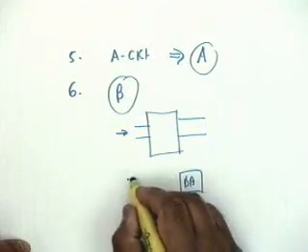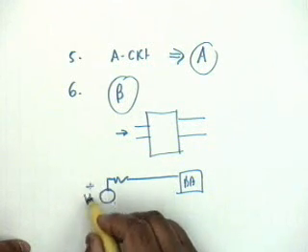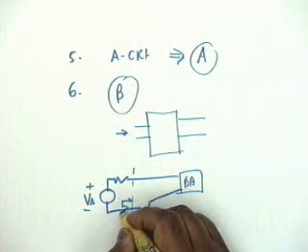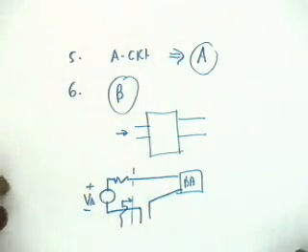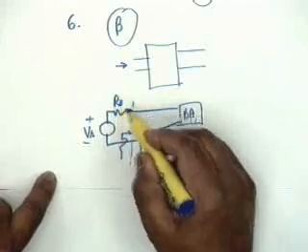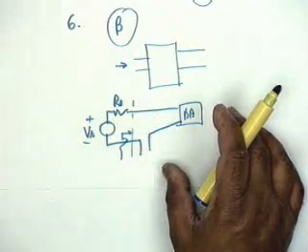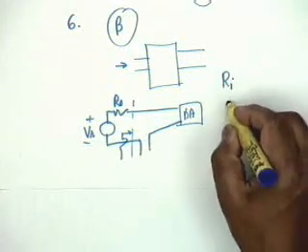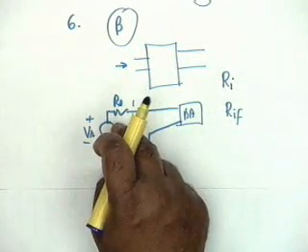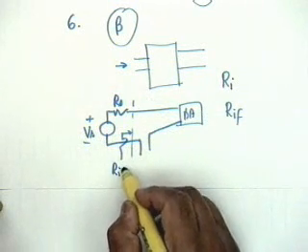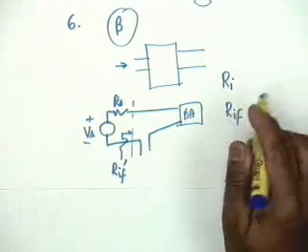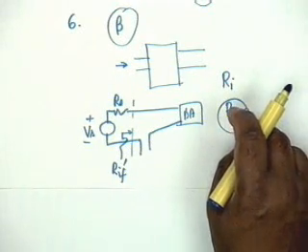Let me make that caution also at this stage. Suppose you have a basic amplifier and you have Vs and Rs, maybe the connection is series. Now, what I actually need is the impedance that is seen by the source along with its internal resistance. When I absorb Rs in the basic amplifier, obviously Rs is inside, and in the feedback amplifier what you find out is Ri without feedback and then Rif, both of which shall involve Rs. Therefore, to find out the actual input impedance faced by the source in the total feedback configuration, you shall have to decouple the Rif that has been found out from its Rs component.